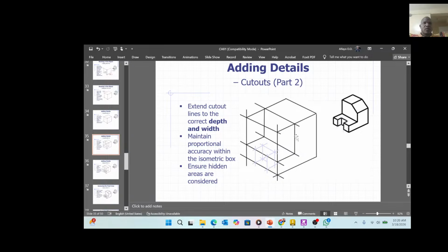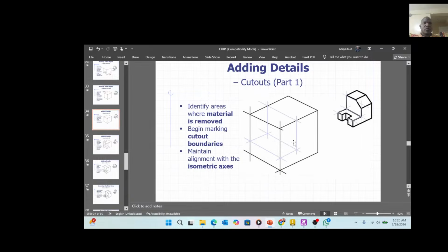Now we've marked. Initially, we started by sketching, and pay attention when I always say the use of pencils, the application of pencils. Which kind are you? Do you use HB? Do you use 4H? Construction lines are drawn by the hardest pencil. The harder the pencil, the lighter it draws. And as you can see, I've differentiated between the outline and also the construction line here for your understanding. The same way it's applicable in manual drafting, which is very key to us.